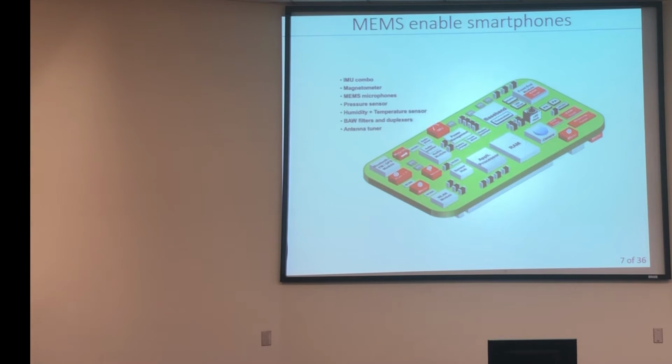This value gives you an idea of the amount of energy lost per cycle as things vibrate back and forth. Having a very high Q enables something to tune into a particular frequency and filter out frequencies that are right next to it. That's how you get really high frequency selectivity.